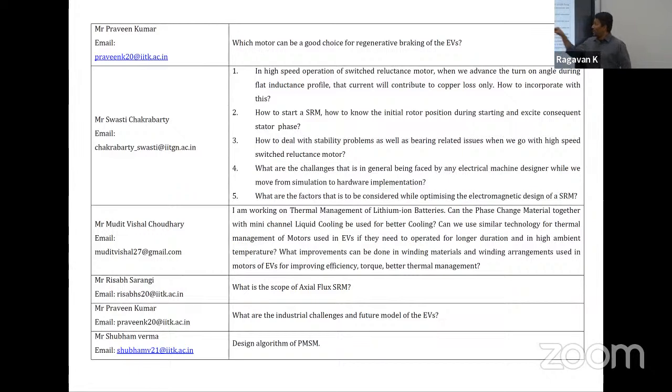But when you're implementing this, expect that the numbers will be lower. That's almost always going to happen. And pay a lot of attention to your gate driver. Whenever you're designing something, one of the key components is a gate driver. Switch selection is important, but the gate driver circuit makes or breaks your design in most cases.